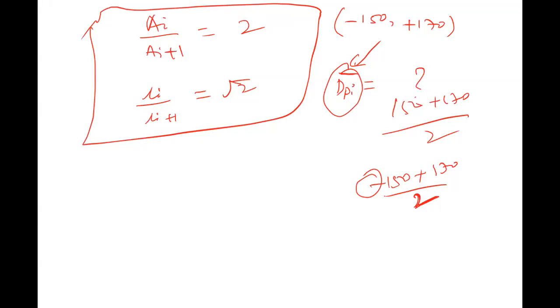Sai Sudarshan, is your doubt clear or not? Because you said 10, because you already took the minus value. So there is a chance of making a mistake here. So always remember, negative sign indicates that the particles have passed through the screen, and positive sign indicates that materials have been retained on that screen. So next, write screening. Yes, 150 and 170 are the mesh numbers. Undersize and oversize. For a particular mesh, there is an undersize and oversize, negative and positive.